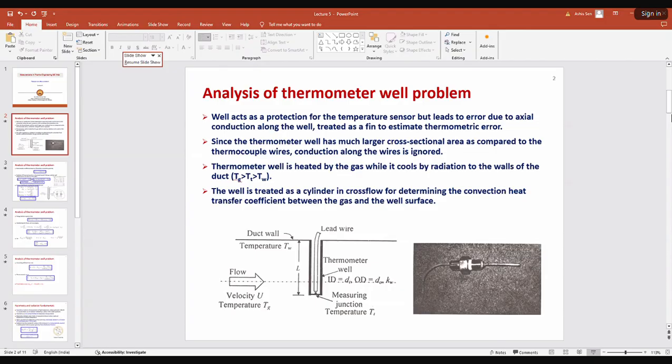See, the tube wall has so much conduction happening along the length of the tube wall. Whatever heat response is coming from the fluid will get conducted in this direction, and nothing much may reach into the tube.